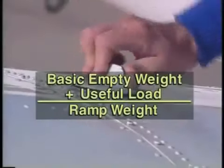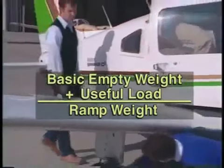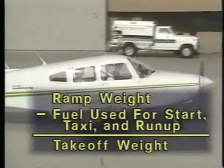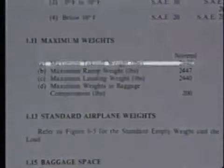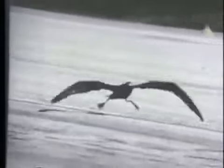The sum of the basic empty weight and the useful load is called the ramp weight, which is the weight of the aircraft during ground operations. You adjust ramp weight by subtracting the fuel to be used for engine start, taxi, and run-up to get takeoff weight. This weight should not exceed the maximum takeoff weight found in the POH or the weight and balance records. If your airplane is too heavy, it might have trouble getting off the ground.